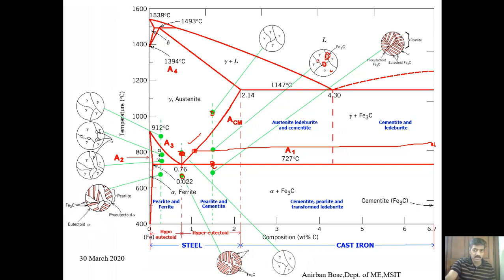And here you can see one more thing, that these cementites are forming at the grain boundary region. The reason is very simple: grain boundary regions are the defective regions, so they have higher free energy. So the chance of nucleation of these solids, the probability will be more that they will form at the grain boundary region. That is why you can see that at the grain boundary region, pro-eutectoid cementites are concentrated, and the remaining portion will be formed by pearlite, alternate layers of ferrite and cementite.